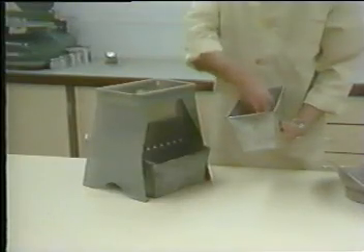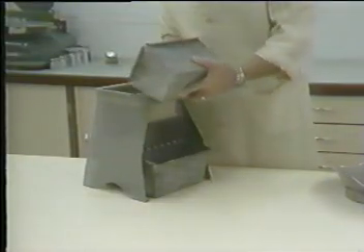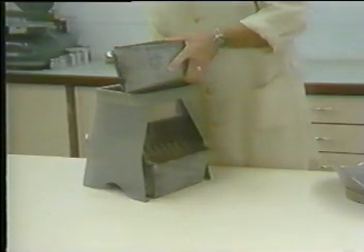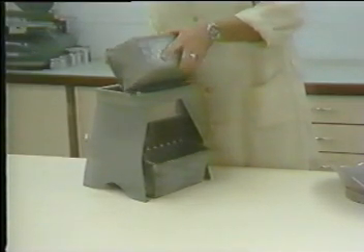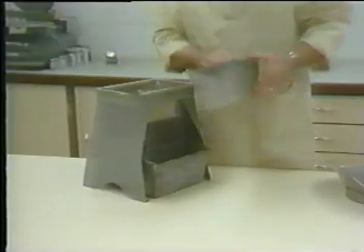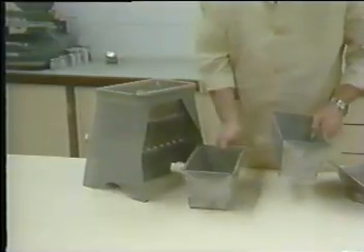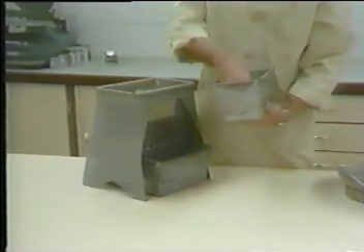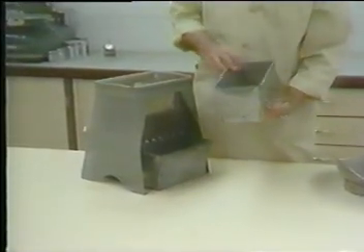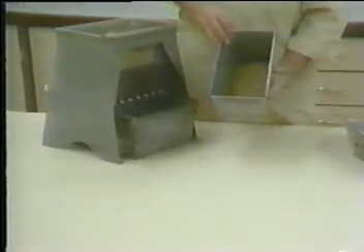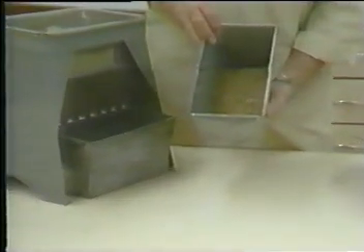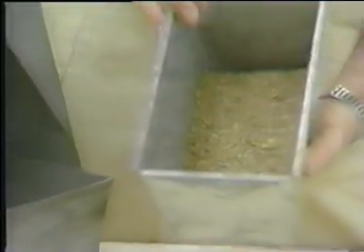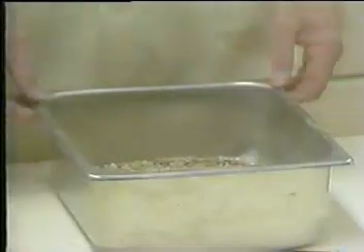To prepare a sample, obtain a quantity of fine aggregate in accordance with ASTM D75 sampling aggregates. Separate approximately 1 kilogram of the fine aggregate from the sample using ASTM method C702, reducing field samples of aggregate to testing size. Dry the test sample in a suitable pan or vessel to constant weight at a temperature of 230 degrees Fahrenheit plus or minus 9 degrees.